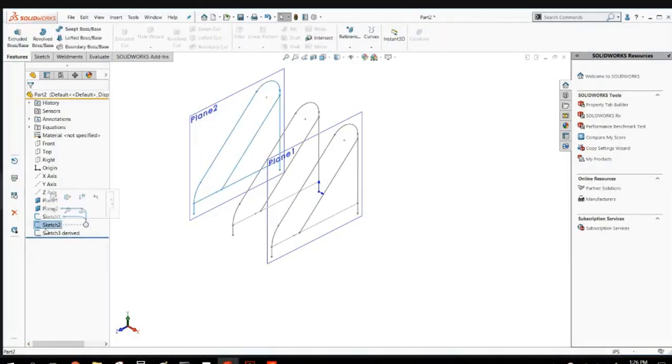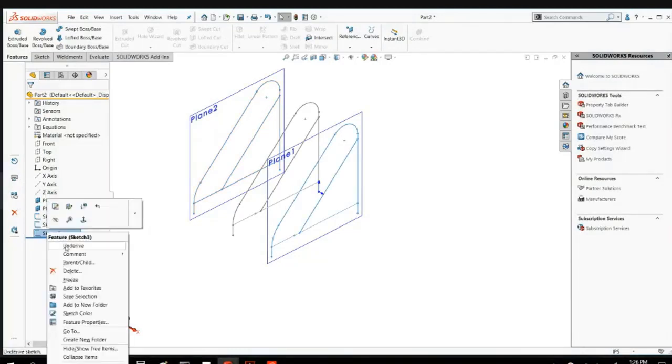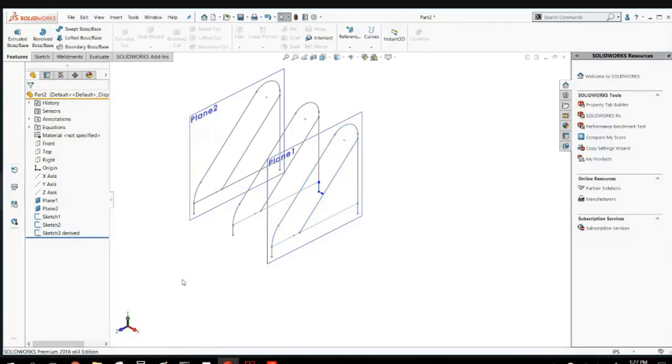This one is a derived, converted sketch. This one is derived. If at any time you want it to not be an exact copy of the original, you can underive it. It becomes its own independent sketch. You can put dimensions in it. It will not affect the original. Be aware that there is no rederive. Once you have underived a sketch, that's forever going to be the way it is. It just turns it independent. So be careful before you underive it if you don't know what that means, but just to let you know what's going on there.